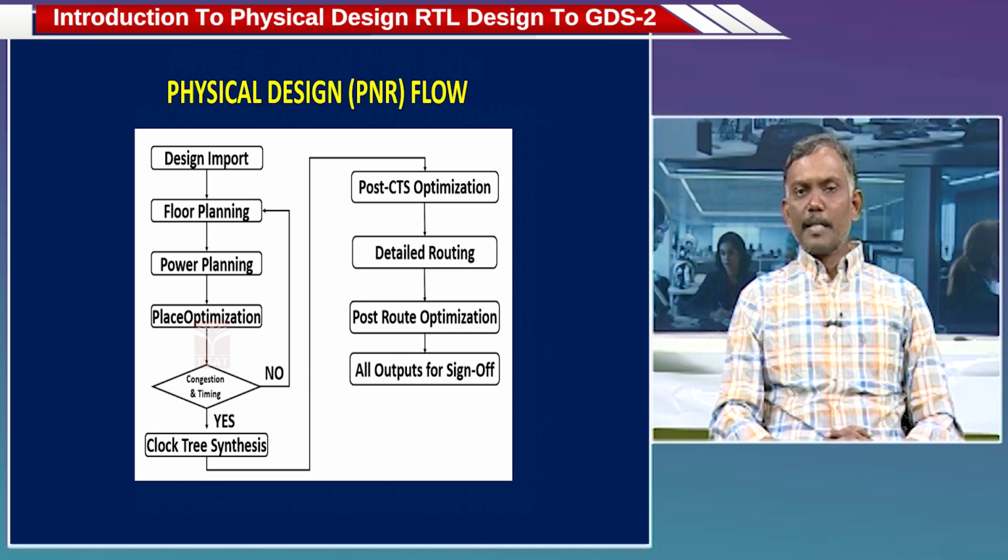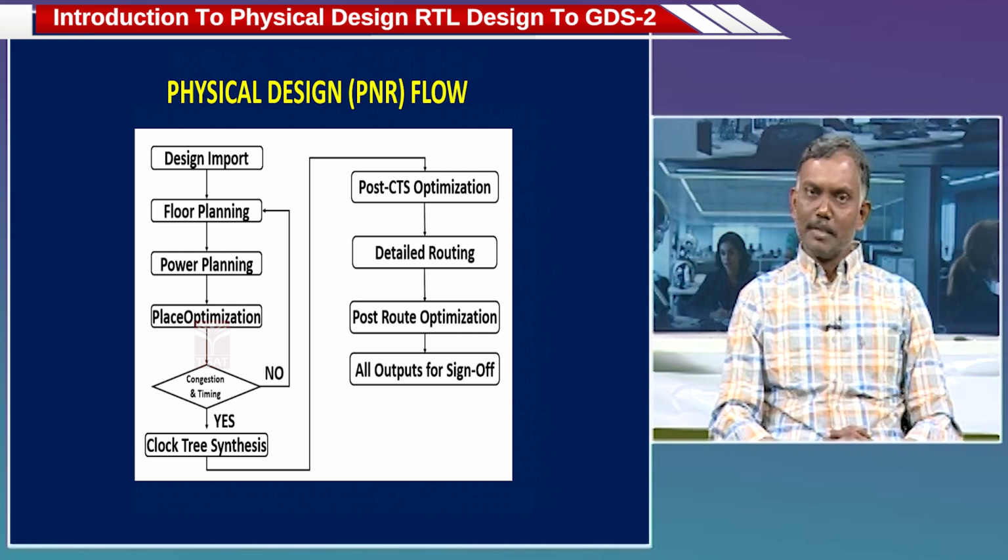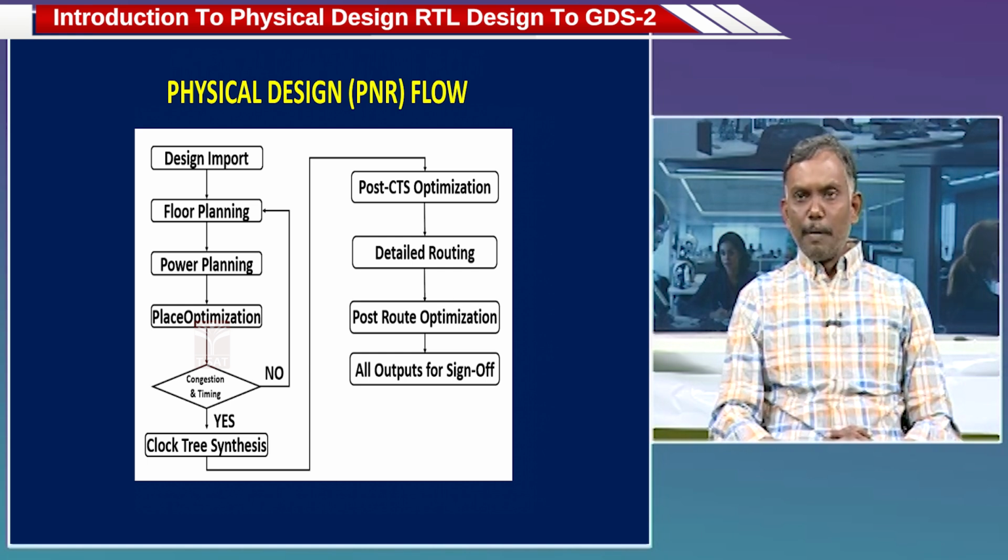Placing of bigger components. I will explain more details in the coming slide. Next one is the power planning, power and ground connections. Next one is the place optimization. To meet our timing targets, power and area targets, we should go for the place optimization.